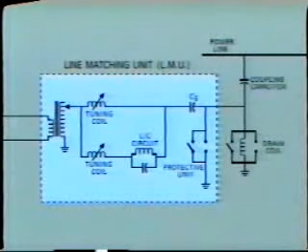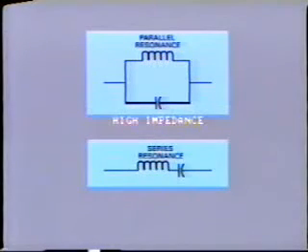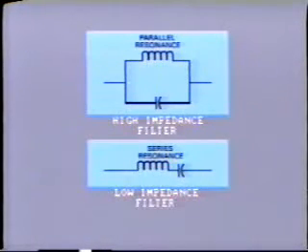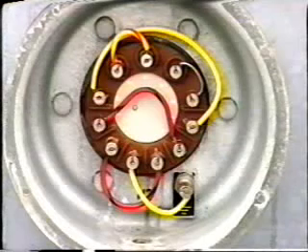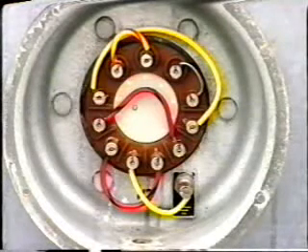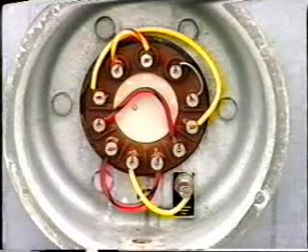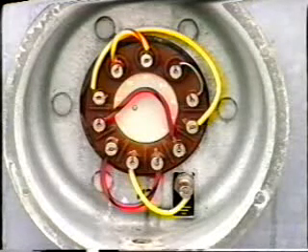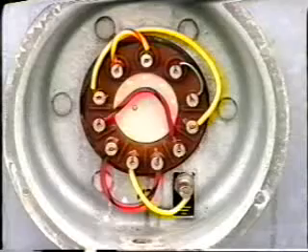In order to achieve this, the tuning circuit becomes more complicated, with a combination of inductors and capacitances arranged in series and parallel. Remember, parallel resonance provides high impedance at its design frequency, in contrast to series resonance, which provides low impedance. These circuits are often known as filters because they allow only the desired frequency currents to pass. Connections between the many inductors and capacitors are made at the terminal board by metal conductor straps. For this reason, the initial test and tuning is often known as strapping.